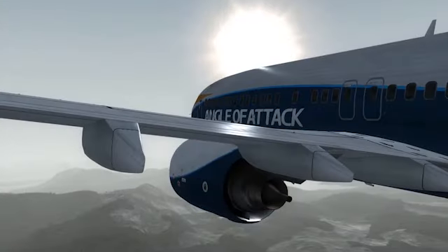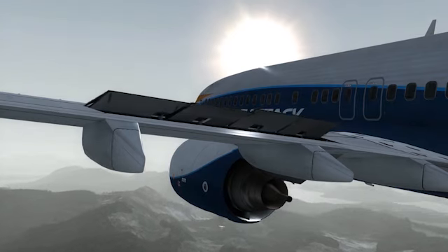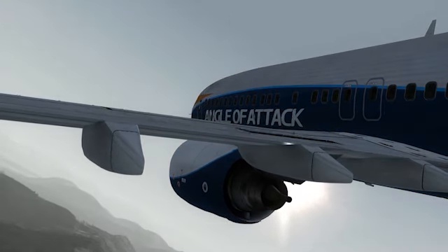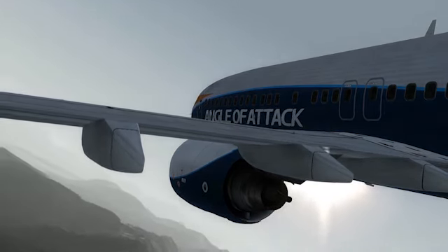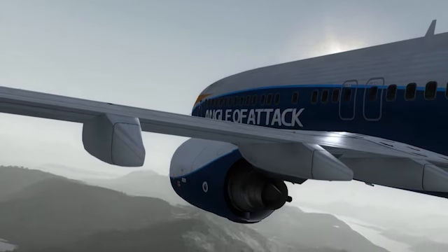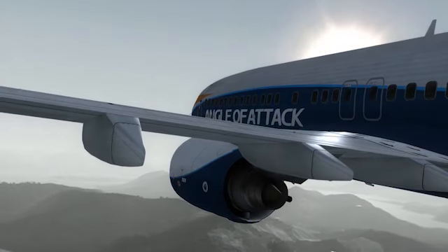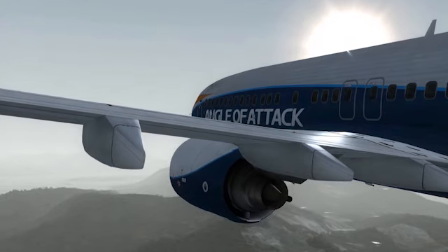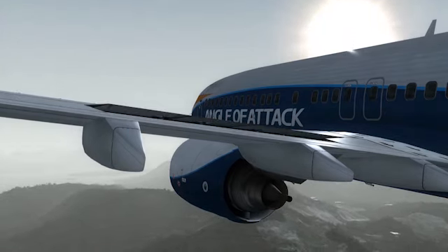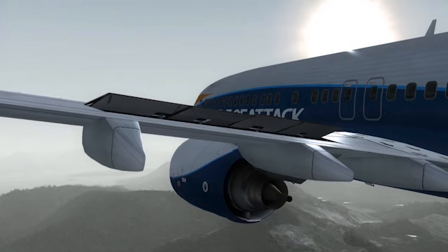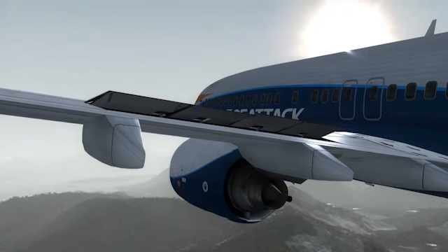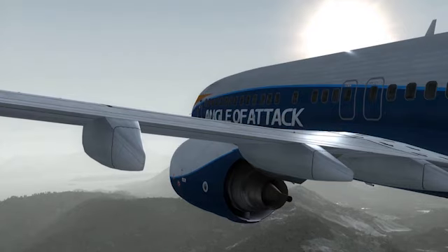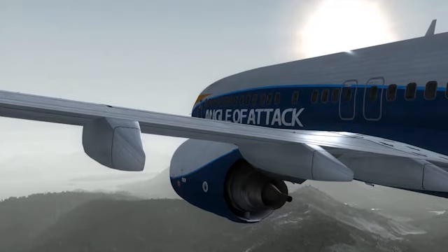During roll, when the control wheel turns left, the flight spoilers on the left wing move up, and in the right wing, they stay faired down. Flight spoiler panels on the 737NG have numerous functions, such as aiding ailerons in achieving roll control, aileron trim, speed brake operation during flight, and speed brake operation on ground during landing.